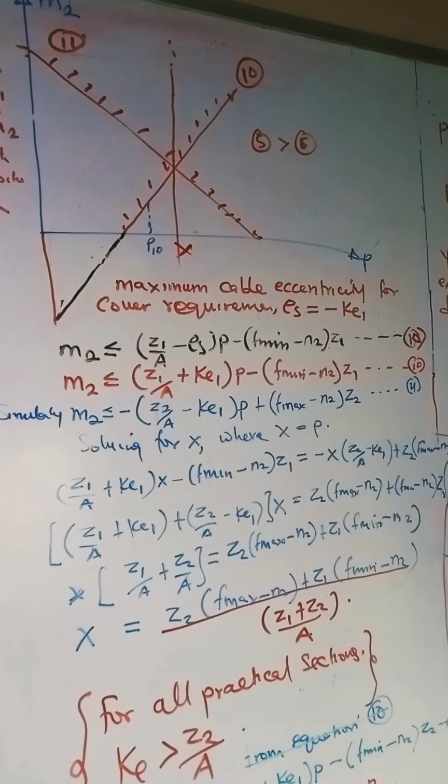If you are carrying out a design and, due to high moment, there is need for a pre-stressing force greater than x, it is recommended that you peg your value at x, or better still lesser than x, and you can choose around that zone. Any value above x for pre-stress is going to be uneconomical.